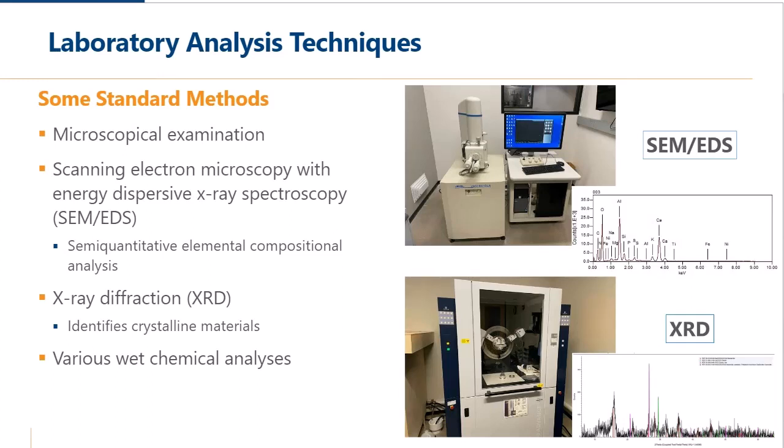To help understand variations in the performance of a material in service, we generally recommend subjecting materials exhibiting degradation to comparative microscopical or chemical analysis. This allows us to compare the chemical and physical properties of a sample exhibiting distress to a sample of the same composition that was minimally altered in service and hopefully resolve what's causing the distress.